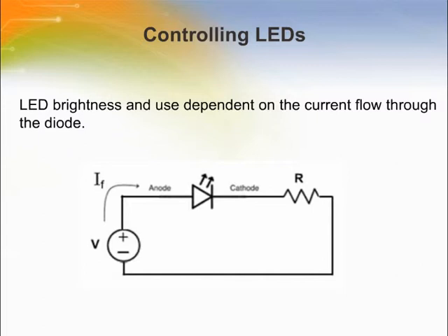However, one of the key advantages of LEDs is its long lifetime. That's only true, though, when the LED is operated within the manufacturer's recommended current rating. Delivering proper power to an LED system is crucial to maintaining correct light levels and life expectancy of the LEDs. Therefore, more complex drive circuits are typically used.